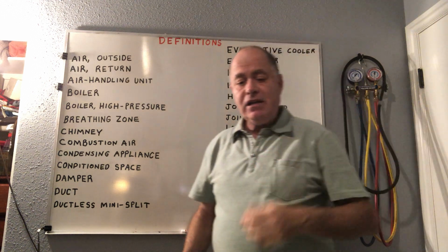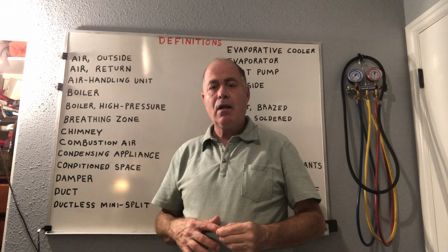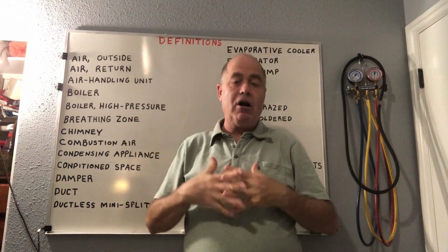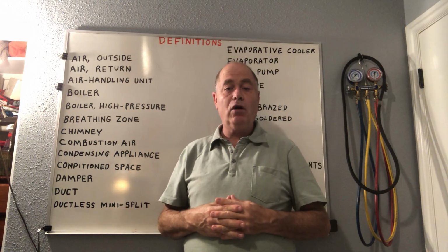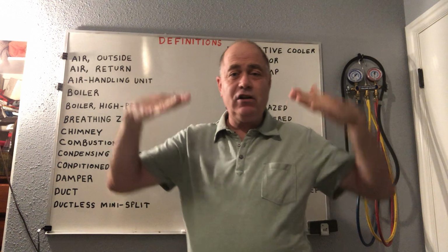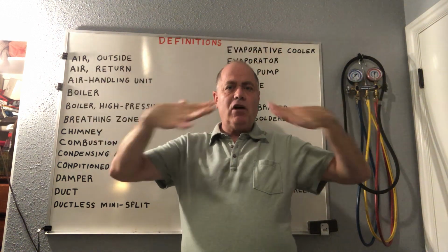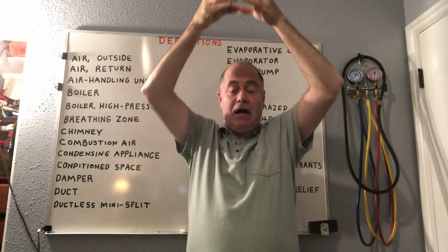We also have, as part of combustion air, dilution air, which is air that will dilute the products of combustion when you don't have a power venter or a combustion blower. Think of a hot water heater, how there's that little space at the top and it can draw air in along with the products of combustion going up that vent pipe or chimney pipe, right?